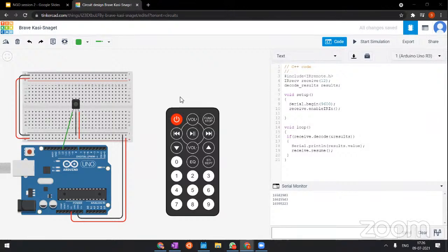And another cool thing is that since this is infrared, you will not be able to see the signals. But if you want to look at it, some of your phone cameras might have their IR filters enabled. So if you somehow disable them, or if your phone camera does not have the IR filter, you can just point it at the IR transmitter on your remote, try pressing a button, and when you look at it through your camera, you can see a purple color light. I just thought this is a cool experiment that you can try out if your camera does not have an IR filter.